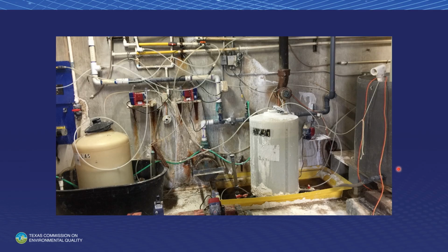The operators were having trouble controlling their chemical feed rates. Turns out that the feed line from the day tank to the ball valve on the metering pump was scaled up. And so the metering pump would operate, but there was no fluid flowing to the metering pump. So while I don't place as much importance on prettiness as Don does, there is a point to prettiness. There is a threshold that you do cross.